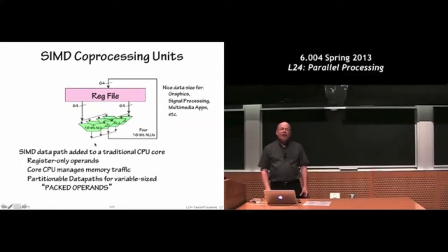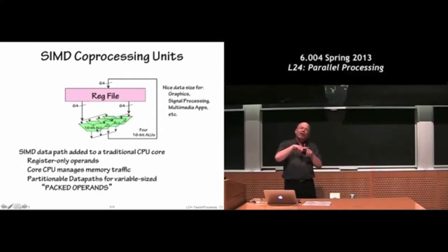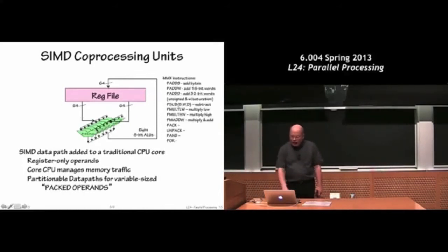So a lot of the video encoding stuff is working on, for example, these little 8x8 macro blocks. That's 64 pixels. There's a lot of operations that are happening in parallel on each of the pixels. So think of this guy as dealing with 4 pixels at a time. Right, so now we're actually using one instruction, just a SIMD unit. One instruction is actually operating on 4 pixels. So instead of taking 64 operations, it'll only take 16 operations using this unit. And that's why these coprocessors are there, because a lot of multimedia stuff these days can take advantage of that. In fact, they go all the way down to 8 bits.